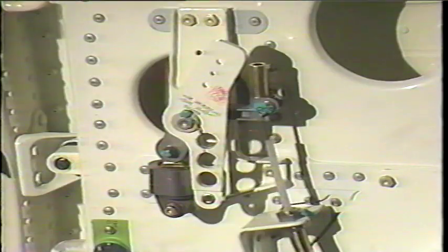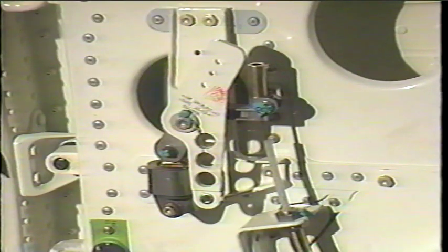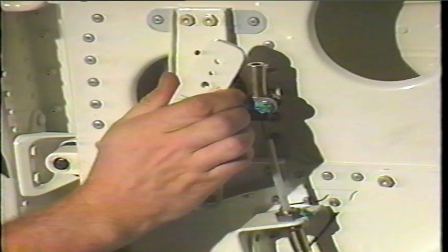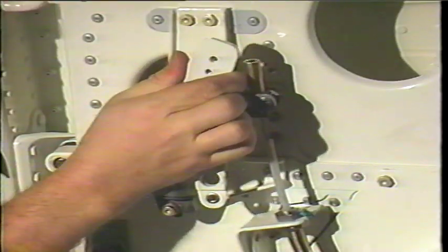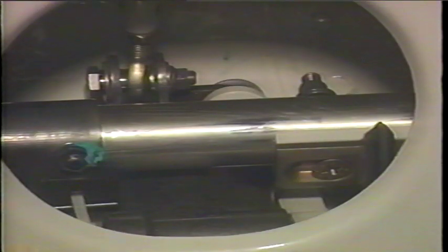To check the lockout cam adjustment, open the door by operating the interior handle and allow the door to move 3 to 5 inches inboard. Try to arm the system by operating the mode selector handle. The lockout cam should block the motion of the crank and prevent movement to the engaged position. If the cam position is satisfactory, tighten the bolt on the lockout cam.